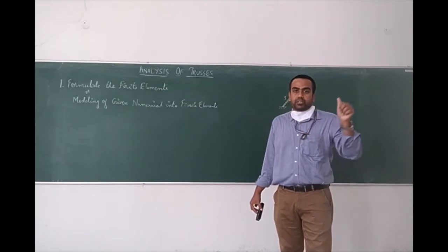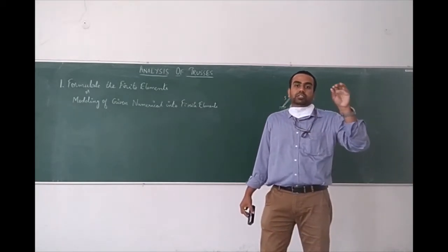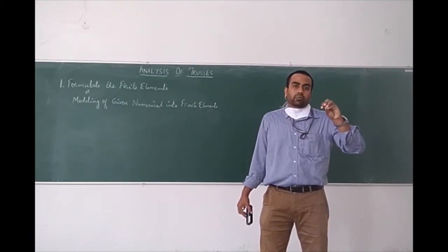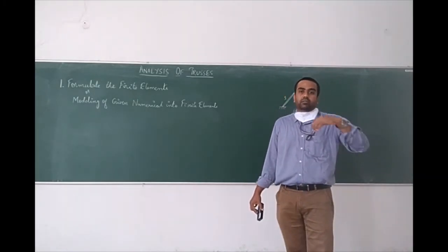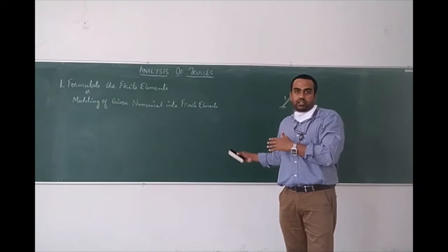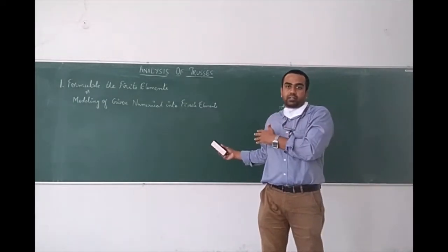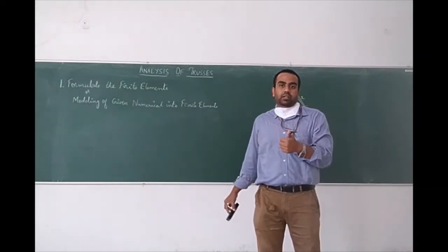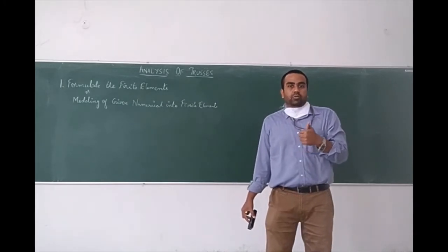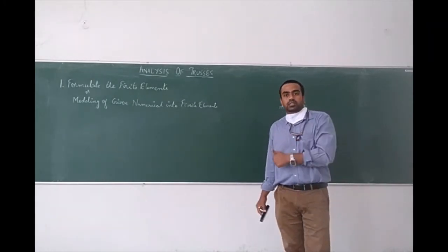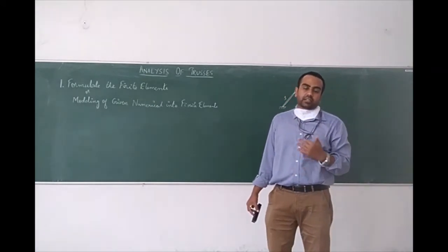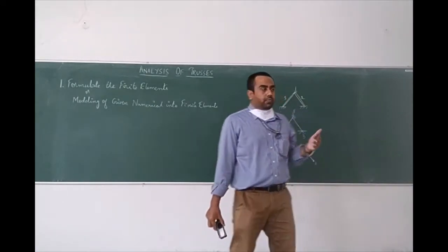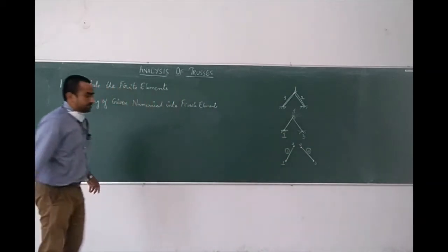From the equilibrium condition, the fifth step is you will substitute the known boundary conditions, and you will take up either the elimination method or the penalty approach method of handling the boundary conditions. From that, the sixth step is you will obtain the displacement values. Once the displacement values are known, the seventh step, if required, is to calculate the stresses and reactions at supports.